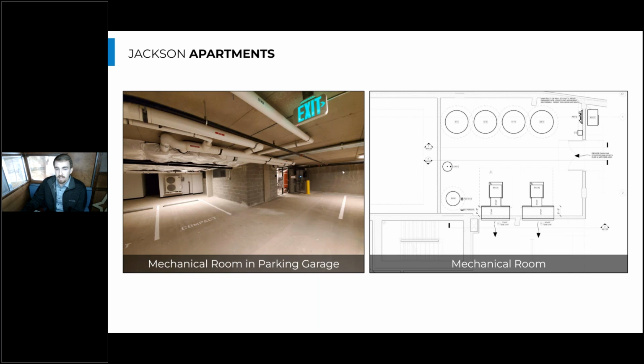And what's happening here is, I'll zoom out a little bit more, the fact that these heat pump water heaters need warm air to extract heat from that air to then put into the domestic hot water. So you need to make sure they have a consistent air supply, usually a pretty high volume flow, and it needs to be warm enough for that manufacturer's requirements.